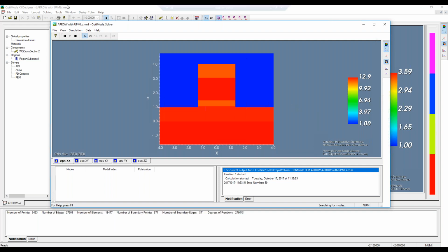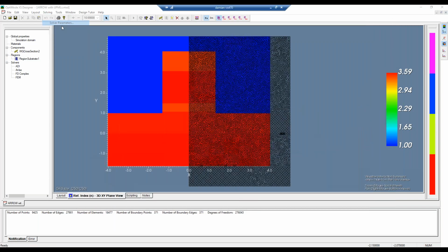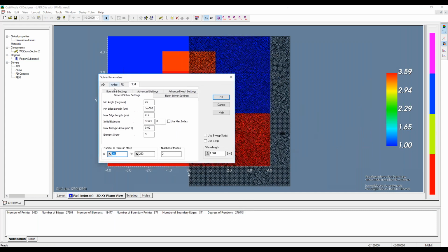While this is going, I'll also just show you the parameters for the absorbing boundary. So we've set absorbing boundaries on the y and the x. This is the thickness of the layer. A larger thickness usually results in a more absorbing layer. This is the order of the grading polynomial. I showed you that function of how you can increase the conductivity profile.